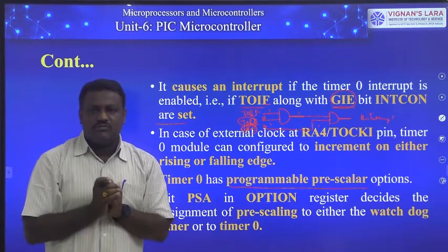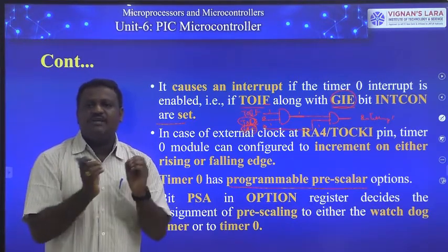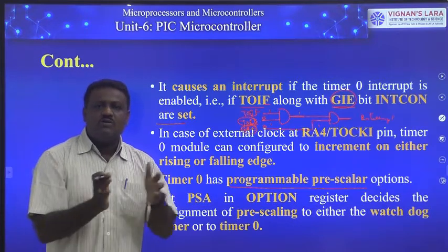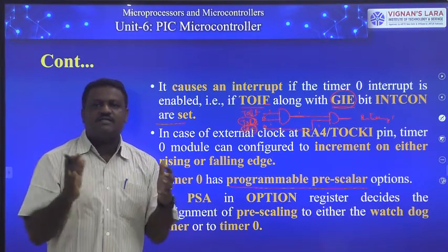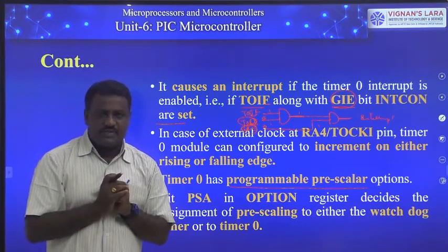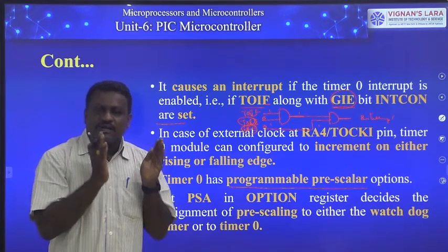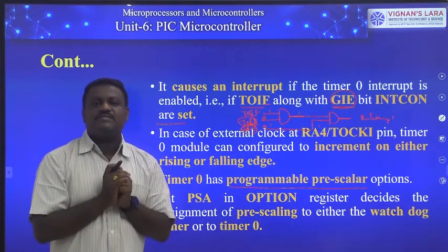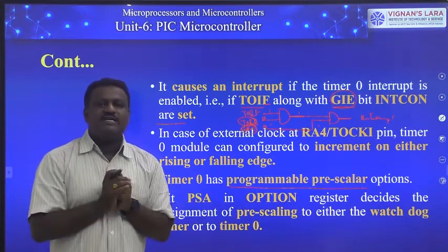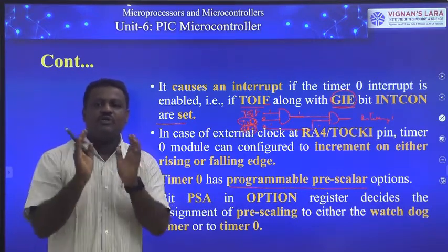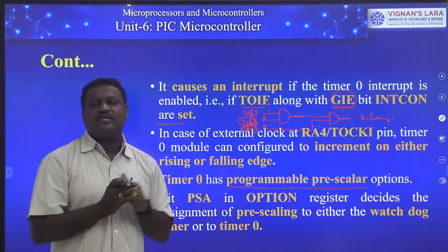Let's assume that counting one clock pulse takes 1 second. Counting to 256 clock pulses takes 256 seconds. But if you want to make a longer time delay with the help of an 8-bit timer 0, without increasing its size, then we take the help of prescaler circuits.